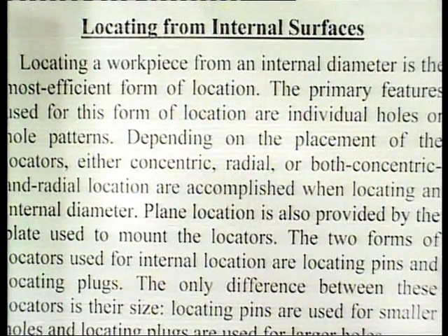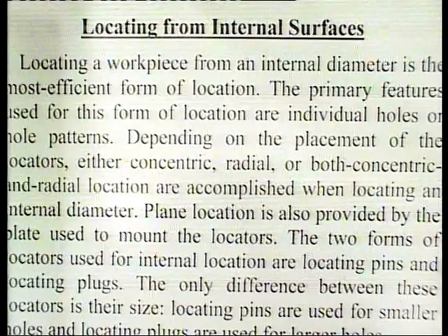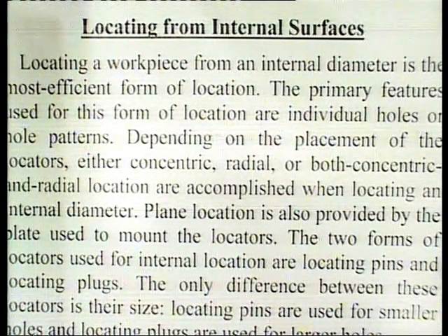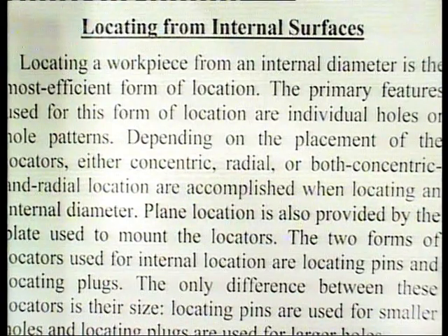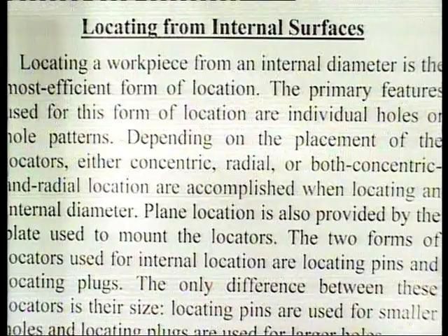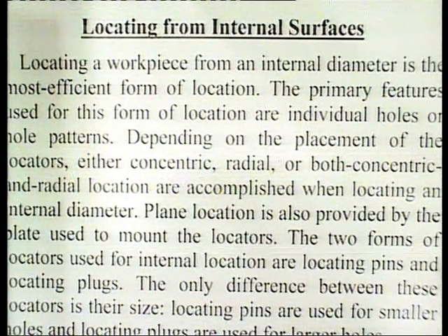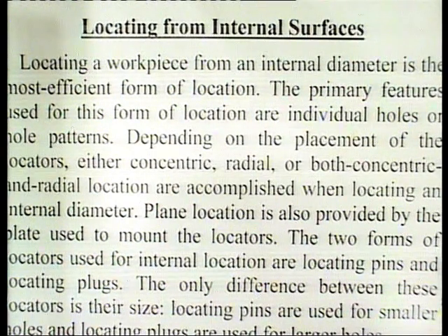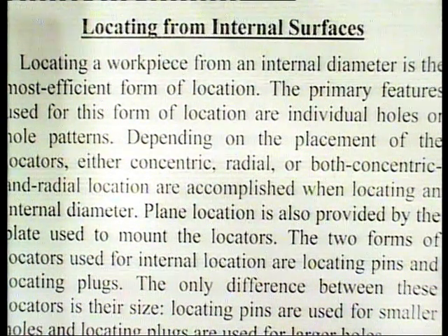So, locating from internal surfaces. Locating a workpiece from an internal diameter is the most efficient form of location. The primary features used for this form of location are individual holes or hole patterns.